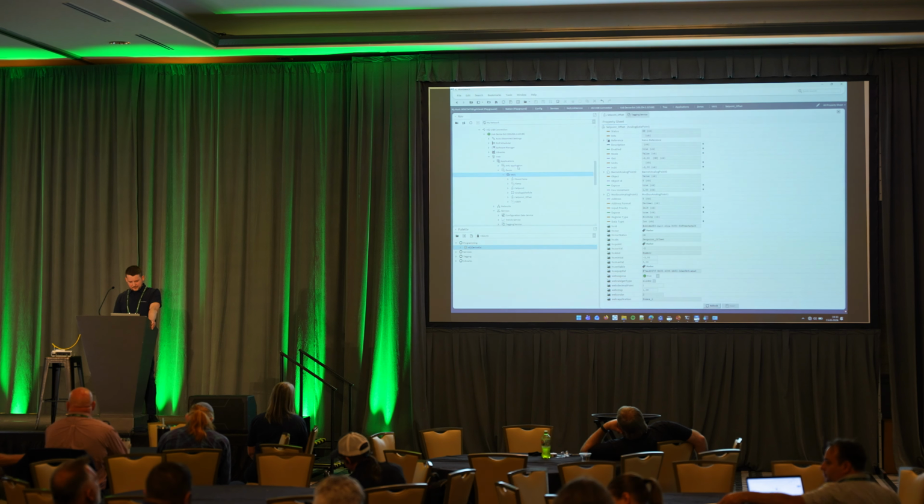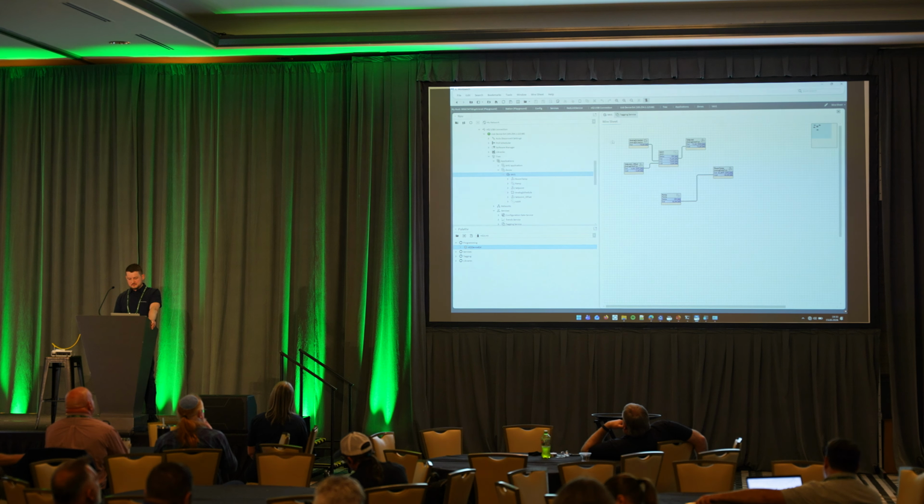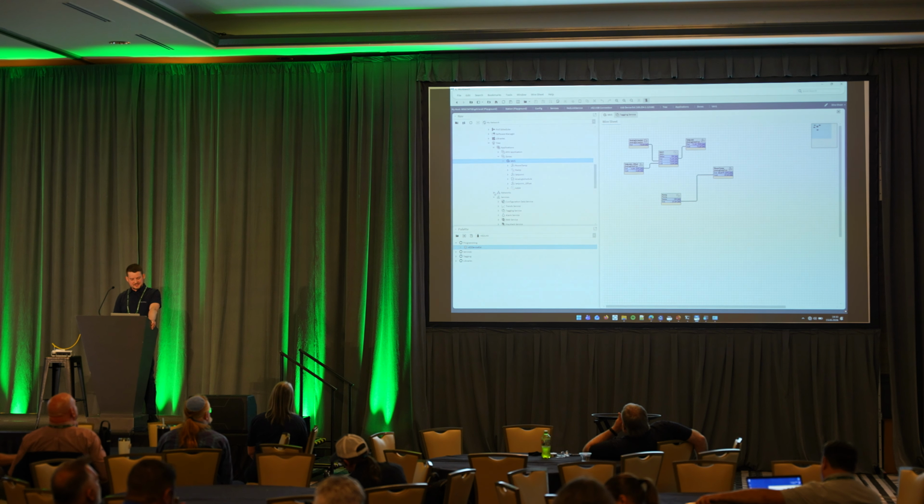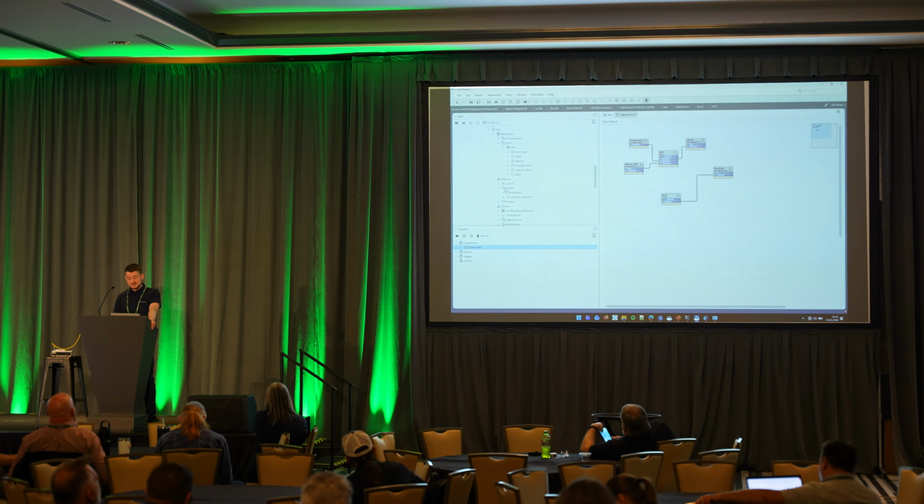So this is one of the core features we have: real-time programming inside the Niagara Workbench, building applications around the data points. All the integration, as I mentioned, will be done here over the networks, where we can also use Modbus and BACnet, and for that we have built views for discovering devices for BACnet as well. So you can bring your devices, link them, create an application, create a visualization.